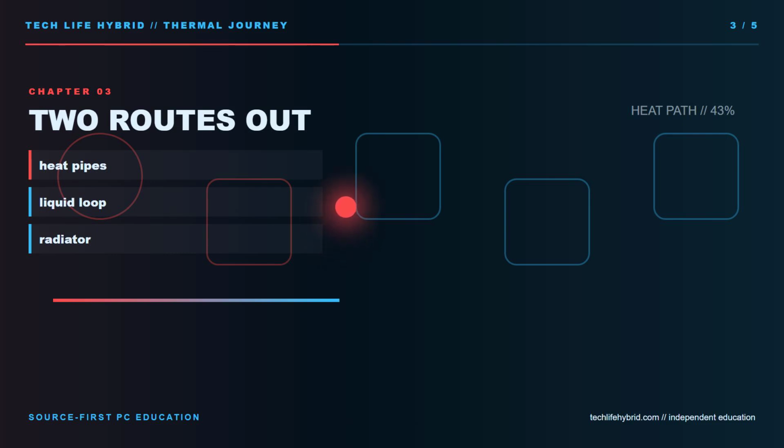Now the heat reaches the case. Intake fans bring cooler air in. Exhaust fans help warmed air leave. More fans are not automatically better if they fight each other, recirculate air, or run so fast that the computer becomes unpleasant. A useful fan curve is quiet during light work and responds smoothly under sustained load. Ambient room temperature matters because every cooler begins with the air available to it.